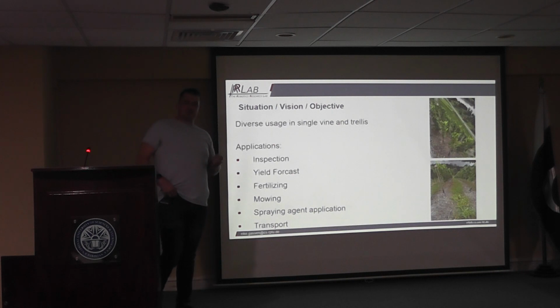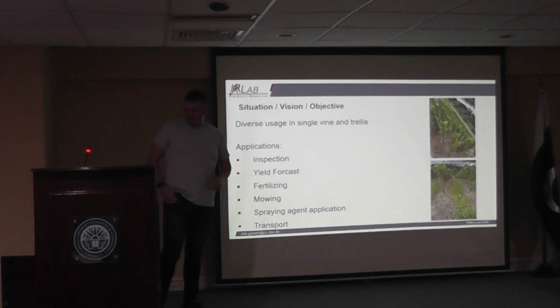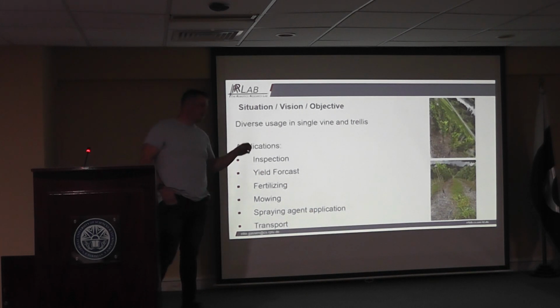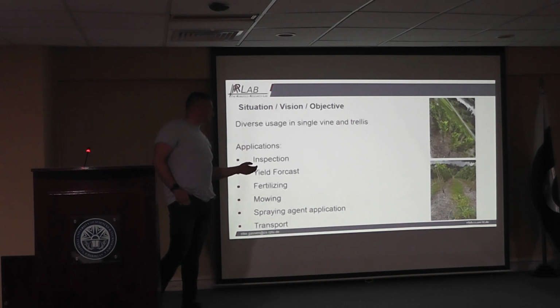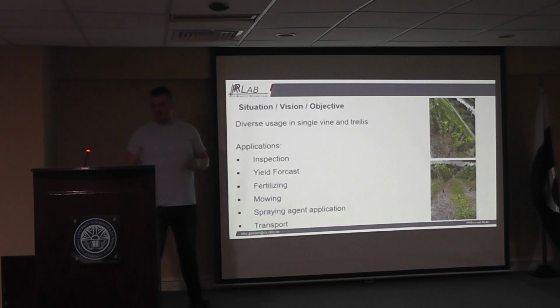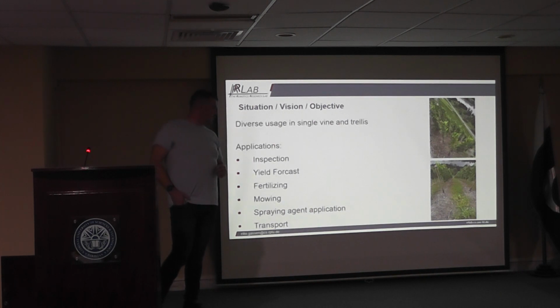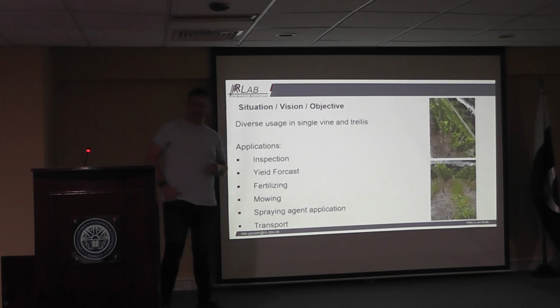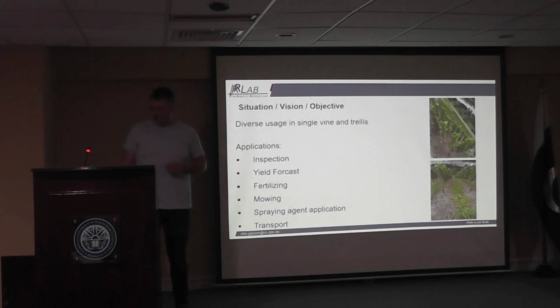Because of that, we made the decision that we have a maximum weight for the vehicle of 150 kilograms, but therefore we got the trade-off that we can't do anything like plowing. There you need a lot of energy to put it up and down, but we can make a lot of cycles driving up and down the slopes, which is an advantage for the winemaker, so that he doesn't have to change the battery every hour or so.